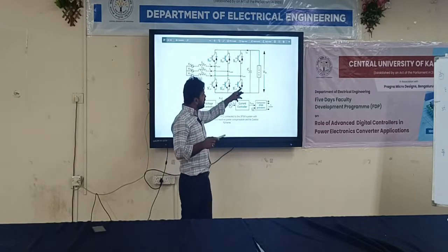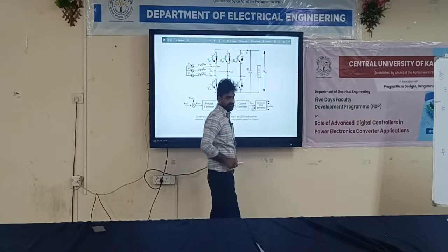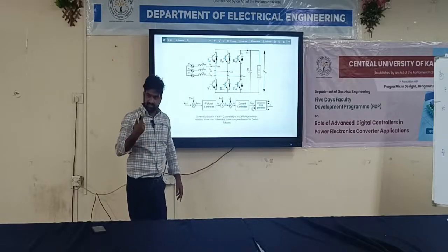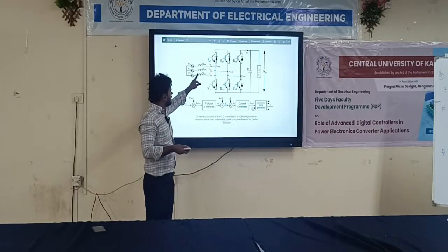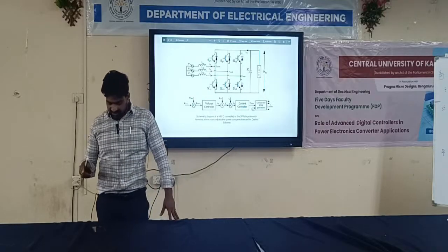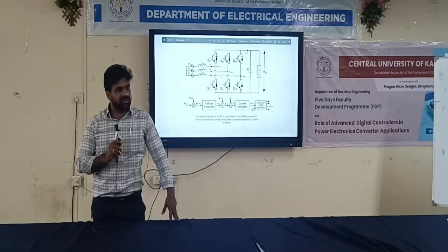That is, even though you increase or decrease the load, the voltage remains constant. And on the other side, your input current should be sinusoidal. That means, what should be the shape of the current that is drawn into the converter? Sinusoidal, and at the same time, it should be in phase with your grid voltage.